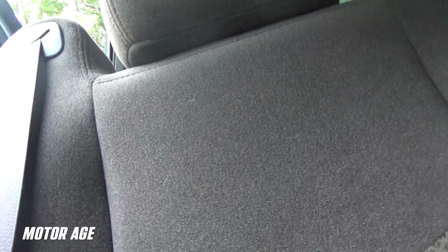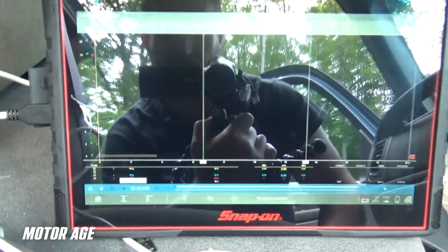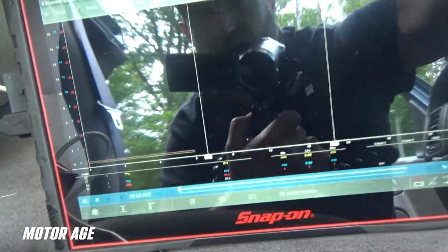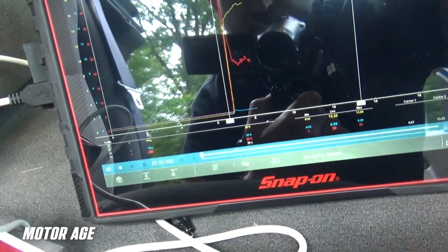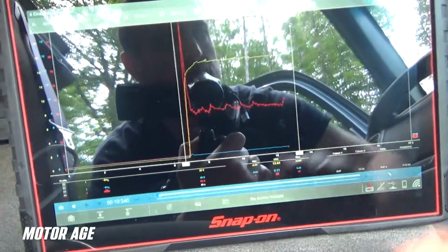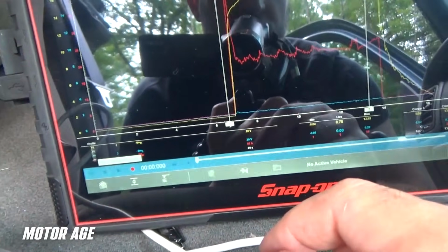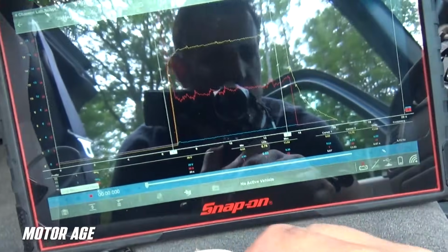So we've got the new blower motor and resistor assembly in. We've still got the scope set up, and we are going to capture current once again, and we're going to see the difference. So with the scope set up, we're going to once again deploy our cursors and go to high speed. Let's pause the screen.